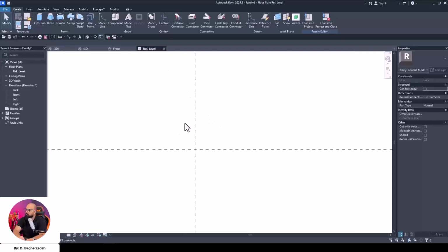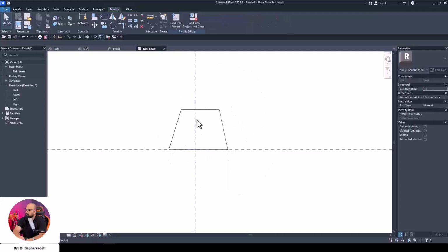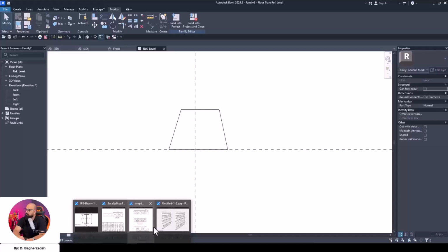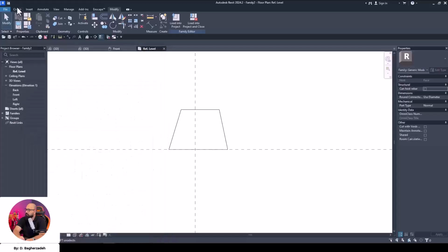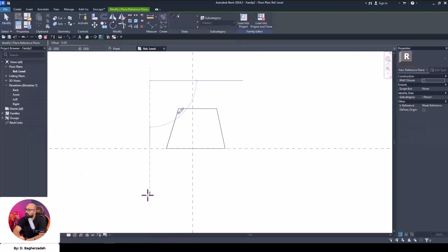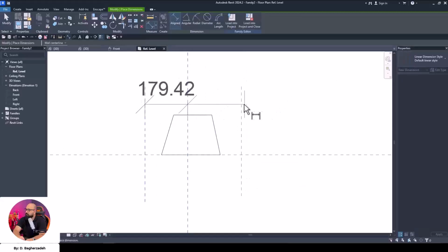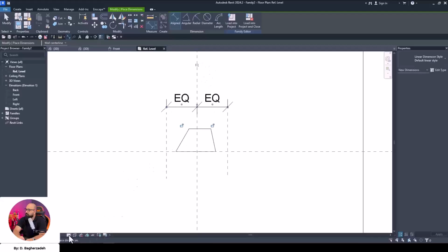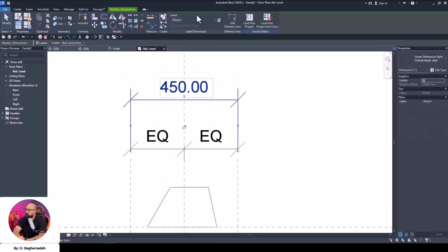Now, what we need here is actually a trilateral, more precisely, a half of a hexagon, okay? Now, for creating this, we can use the parameters and values that we have here. For example, this part is the H parameter. So based on this, back to the viewport, I'm going to press RP as in reference plane. I need one here, and then another one. Now, DI for setting the dimensions. Then EQ for equalizing. Maybe a bit smaller though. Then I need to specify the parameter, which would be H. So here we go. Okay.